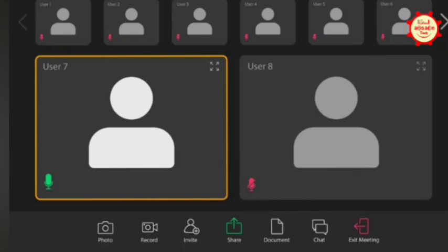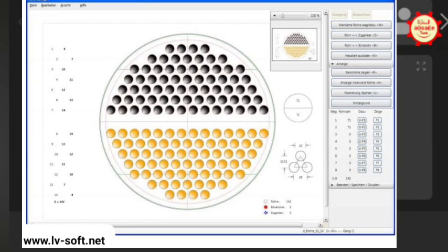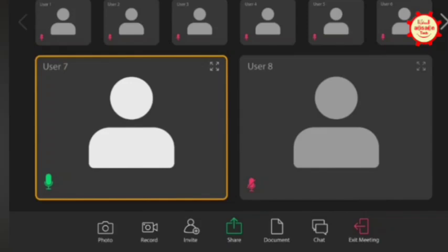While doing programming, you need to consider all aspects like partition plates. That's why the problem is coming: when we consider the partition plate, we have to shift the center hole according to the partition plate location. There will also be a consideration of baffle type. For example, if it is NTIW, meaning no tubes in window, then if there is a window opening, there are no holes on that, so that is not a problem.